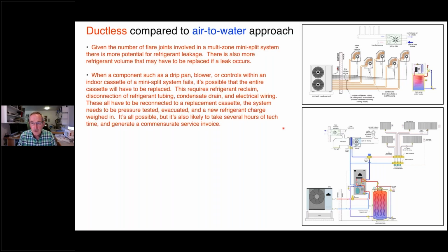So basically, I see these indoor units. They're a highly engineered product. They're very compact. Obviously, a lot of thought went into building something that is that compact. But in doing that, they also become somewhat of a throwaway. Unlike other larger HVAC equipment where you can replace components, they seem to have a tendency that when there's a failure, perhaps there are some units that do have replaceable parts, but in this case, the entire head had to be replaced, and it's expensive, and it took the better part of a full day for that head to be replaced.